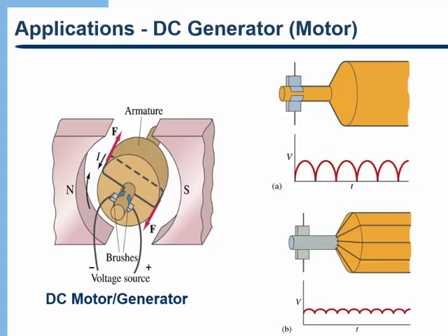By the way, in a real DC generator or DC motor, instead of having just one set of coils in one plane, we have a bunch of other sets of coils as well. And so each of those sets of coils is generating or creating current independently, and they get added up so that the voltage that actually comes out of a real DC generator looks more like that.